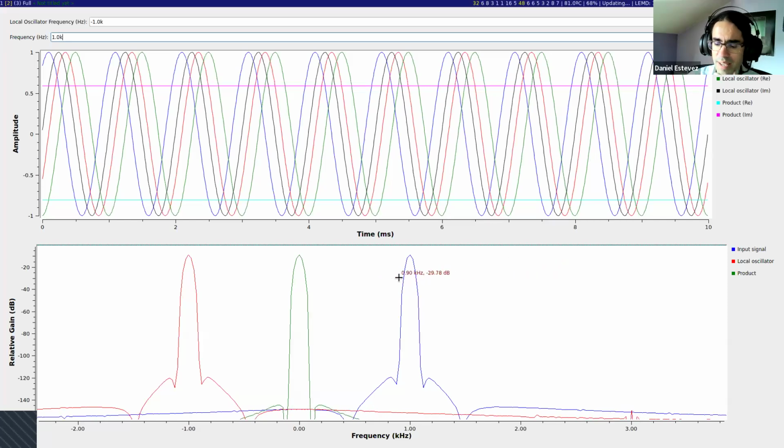So those are the main reasons. And there is also that the Fourier transform ultimately is a complex mathematical thing. In the definition, it has complex numbers. There is no way to have it without complex numbers. And that's the reason why we always have positive and negative frequencies, even with real input signals. What happens with real input signals is we have the same thing on the right and left halves of the spectrum.